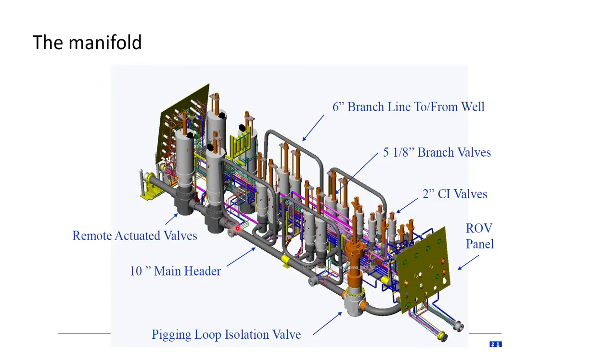Okay, and then it goes and it breaks into two valves. Okay, so these two valves are so big because they are controlled hydraulically, so the actuator is big. Okay, it's a piston, but essentially this can split the fluid either to send it to this pipe, or to a similar pipe on the other side that you don't see because it's covered by all of these lines.